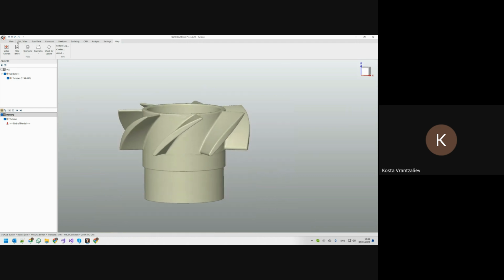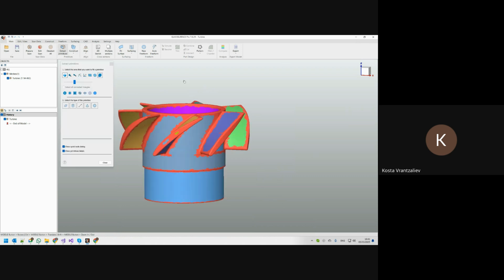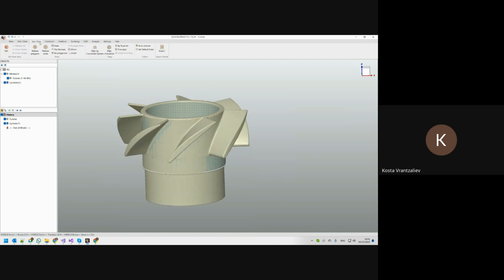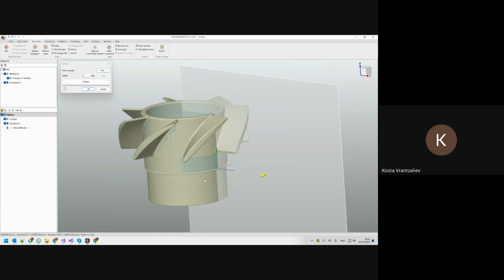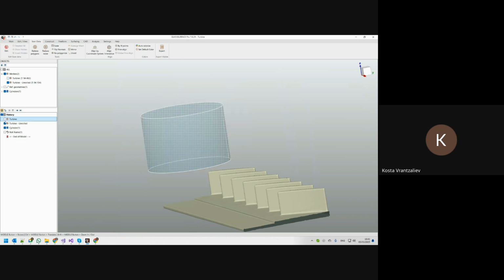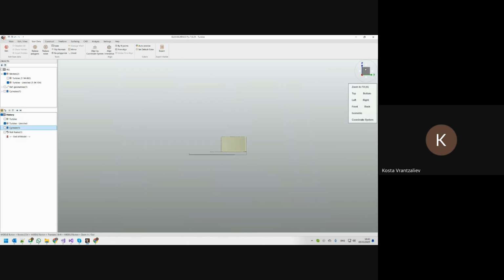So this is a super complex shape here, and let's do a quick unroll. I will just go and make a cylinder. This cylinder is exactly on the z-axis. We'll create it, if you remember. Now I'm going to unroll using this cylinder. Again, you can adjust where it should start, not in the middle of one blade, but probably somewhere here, and I can preview. The magic here is that what you see is actually super flat.